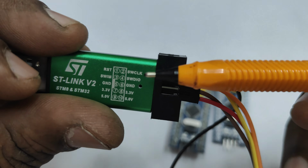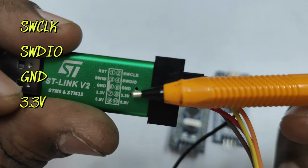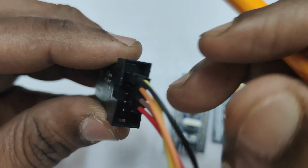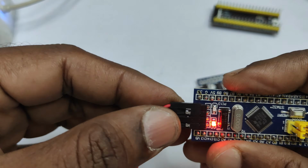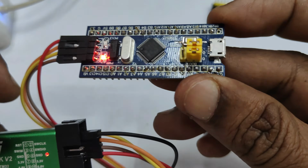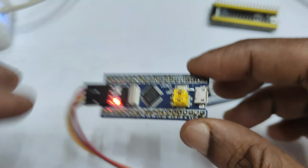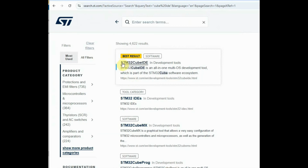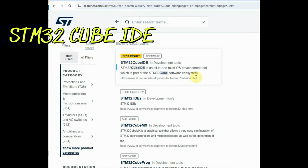Now let us do the one-to-one connection. SW clock, SW DIO, and then ground and 3.3 volt. We'll be using 3.3 volt directly from the ST-Link to the board. Do not use 5 volt as this device is 3.3 volt. Now plug in the ST-Link dongle.